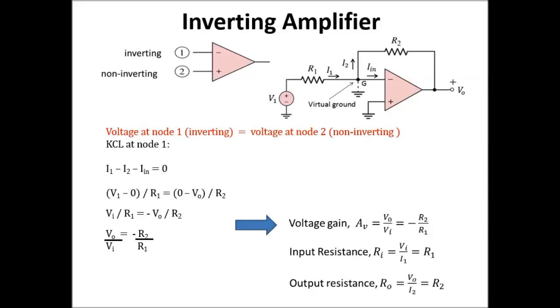So we already know that your op-amp is in the closed loop mode. So we want to calculate what is your Vout over V1 here, which is the input signal. We already established that this is 0 volt because it's grounded, which means that this is also 0 volt. V1 must be equivalent to V2 over here.